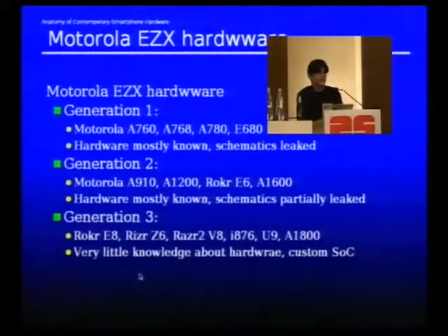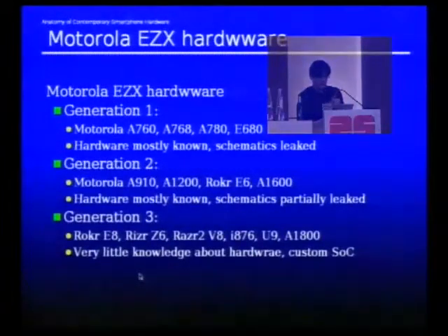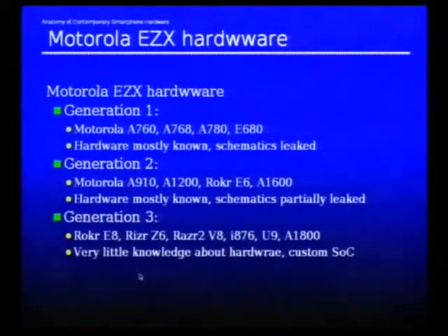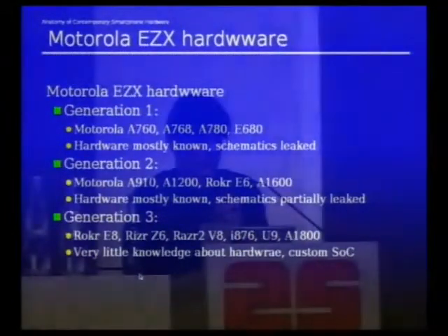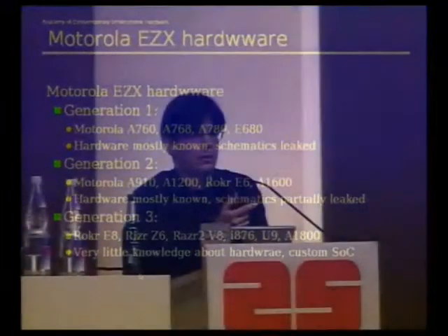The hardware of these devices is fairly well known because the schematics leaked quite some years ago, so people have been able to study them. In all the Motorola devices, we have a couple of key characteristics. One of them is that the audio is routed digitally, so we don't have analog audio between the baseband side and the application processor side. It's a PCM interface. All of these have at least one custom ASIC, which is not a standard component that you could otherwise use. It's the power management unit in those devices.